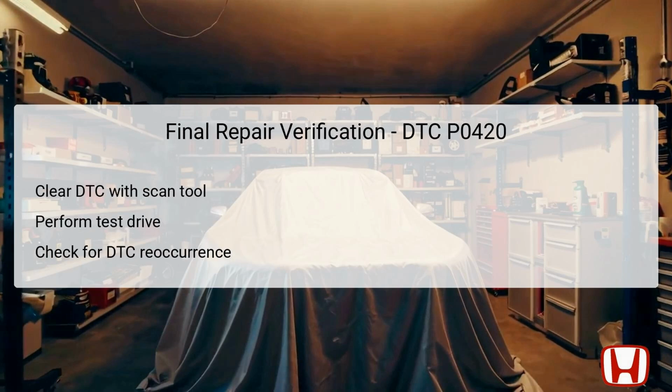After completing all troubleshooting steps related to DTC P0420, it's essential to perform a final repair verification. Start by clearing the DTC using a scan tool to reset the vehicle's systems. Once cleared, conduct a test drive under various conditions similar to those experienced in the earlier diagnostic steps. Pay close attention to any reoccurrence of the DTC and monitor the vehicle's performance during different driving scenarios.